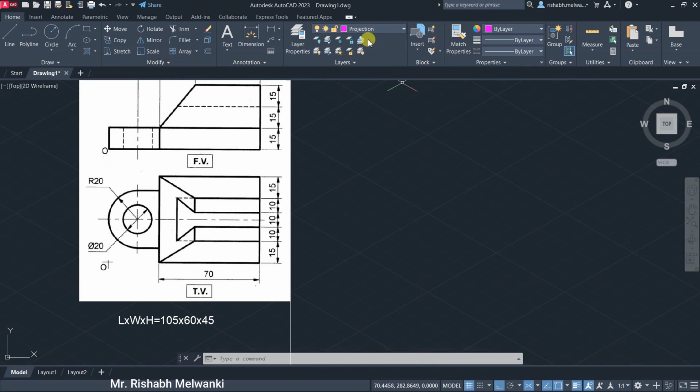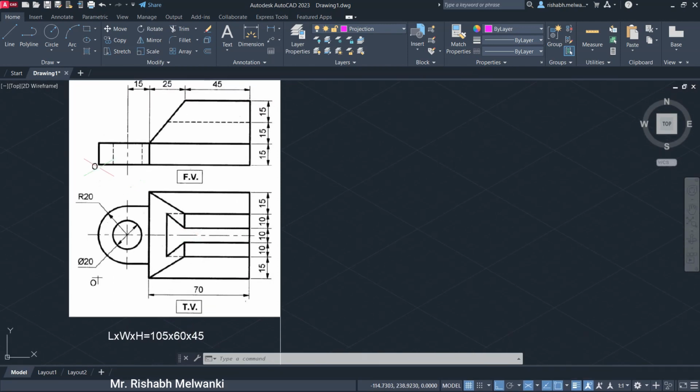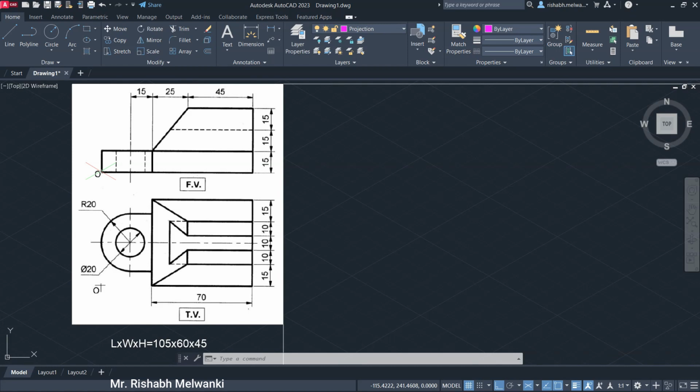Now we will draw the box of the dimensions which are written over here. Remember that since the O is on left side and the dimensions are on right side with respect to point O, O is the origin, so the front view will be on right plane.